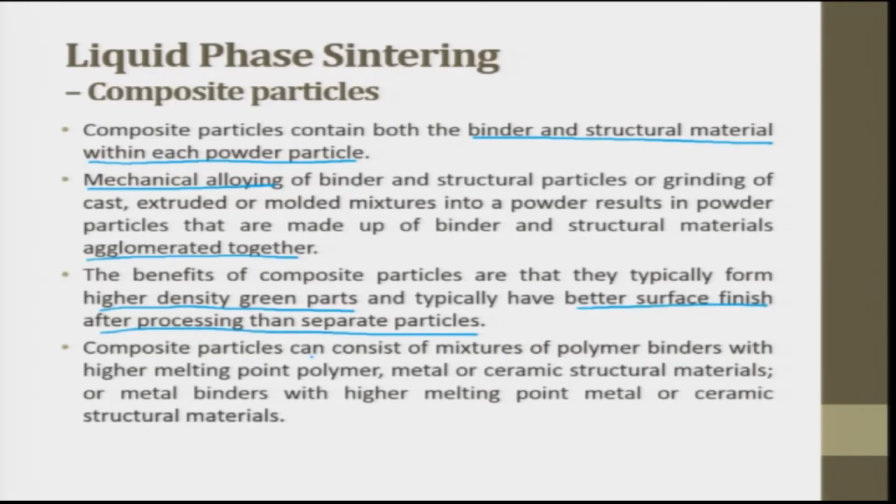The composite particles can consist of mixtures of polymer binders with high melting point polymer, metal or ceramic structural materials, or metal binders with higher melting point metals or ceramic structural materials. So, this is also important. What is that we are doing with each other?